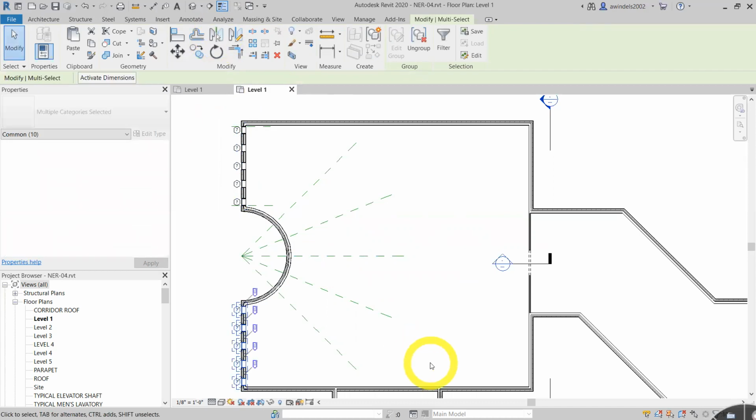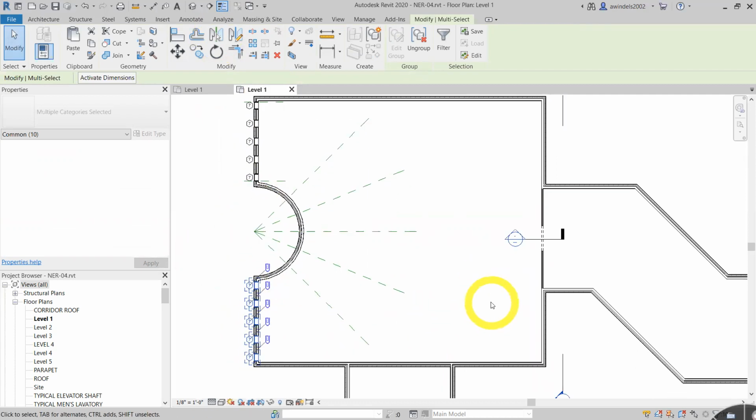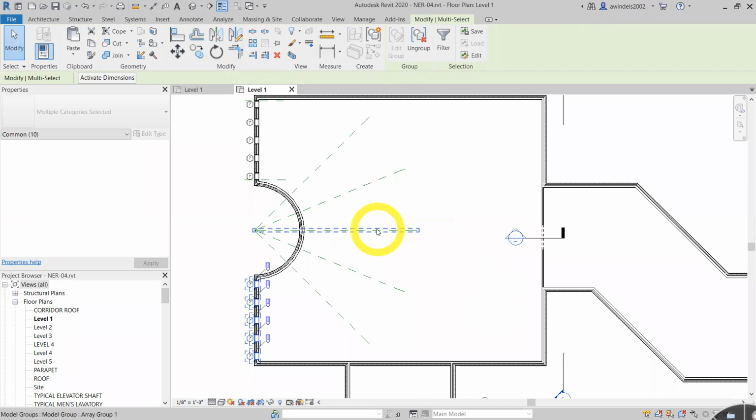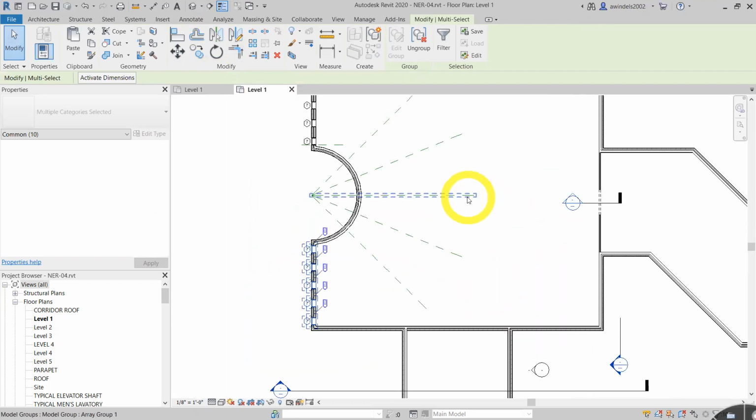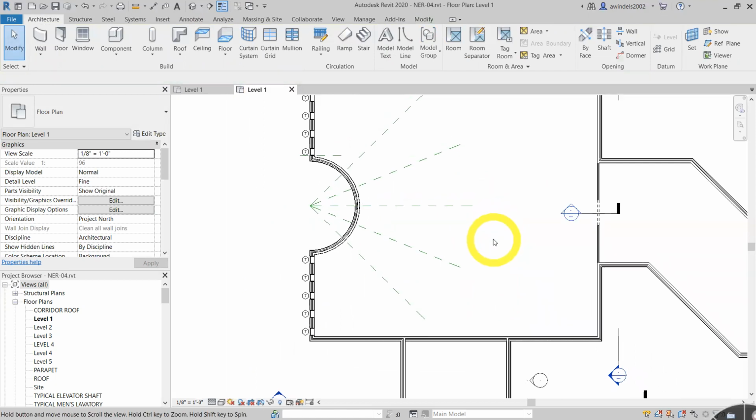If it can't find a wall to attach to, if your walls aren't exactly in the same spot in the X dimension, for example, it will not mirror them. So it has to have a good centered axis, as you saw in your first unit quiz when I made my mistake and didn't have a mirror line in the exact middle. So keep that in mind about that command.